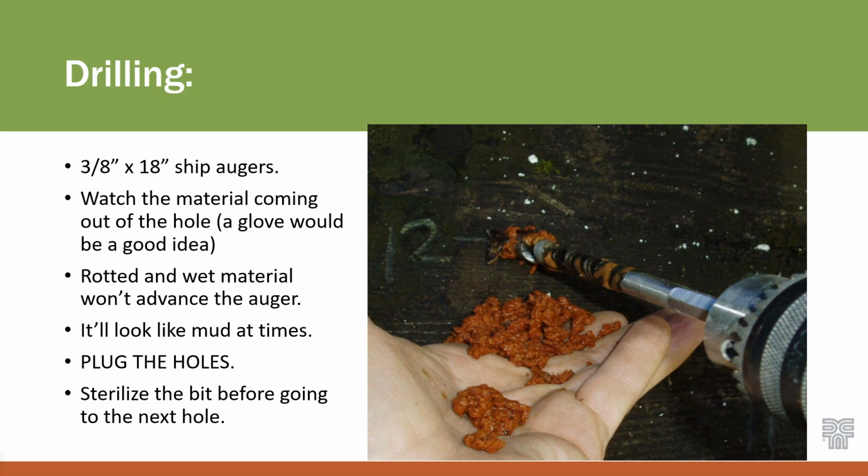Drilling. Drilling is definitely a more destructive method, but it's been around for quite a while, and there's been a constant pull between bridge maintenance and bridge inspectors for as long as I've been around, and certainly before that, of them going out with the hammer method and the inspector saying, hey, this pile's rotted, repair it. And so they go out and cut it out and repair it, and then they come back and say, hey, look, this pile looks great. So what I have always said is drill it before you pull anything out. Drill it as even a first course of inspection.